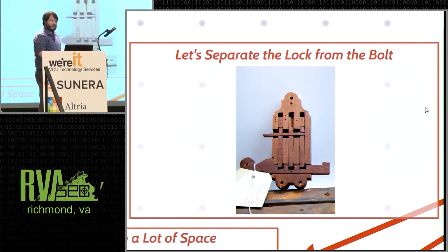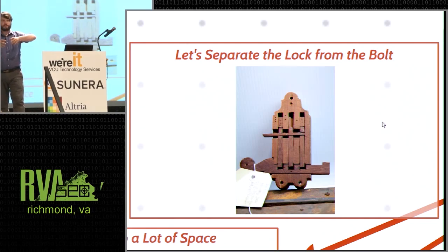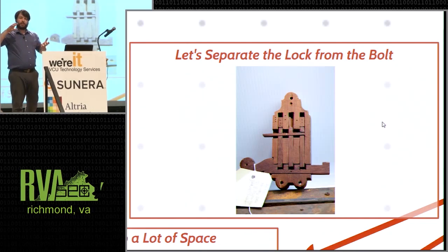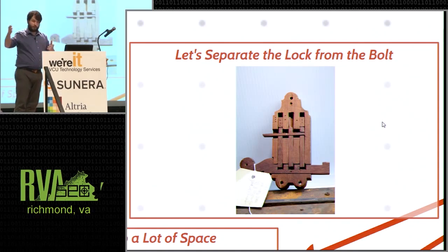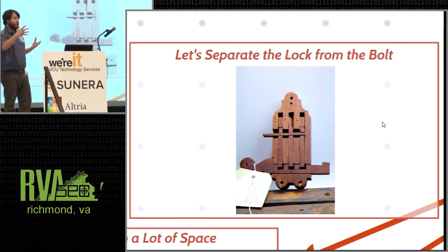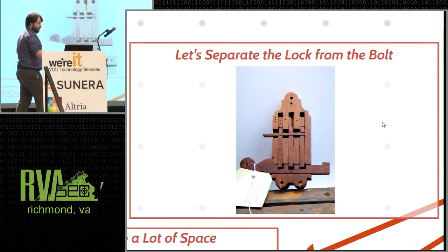hence why people say that this is like this, you would have these sliders with a gap cut out of them. When they were at rest, they would be sitting down into the bolt, but there would be a channel clear for your key to go in. Your key would have a couple of protrusions that were just tall enough to lift that up out of the bolt, and then you could pull the bolt out.